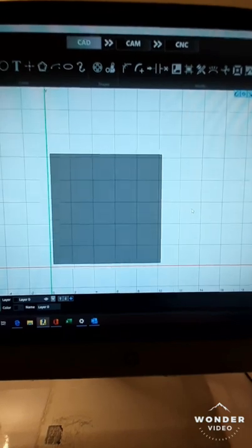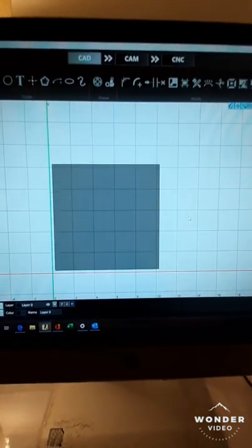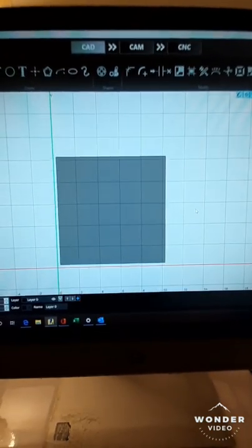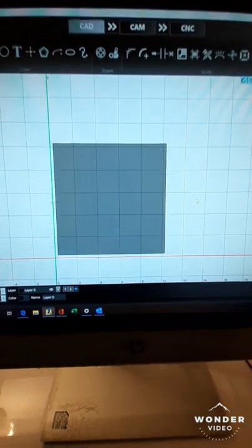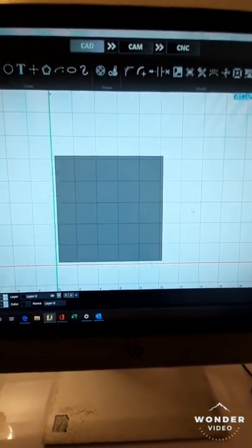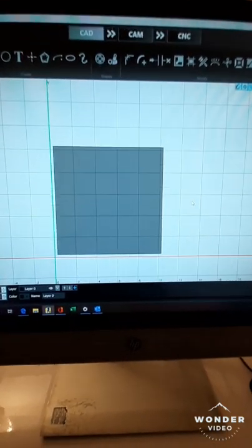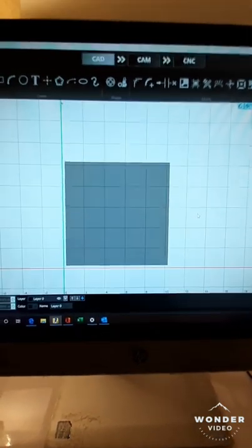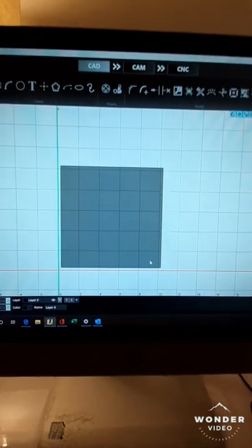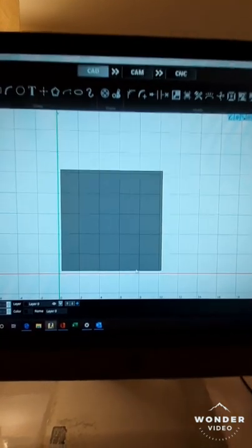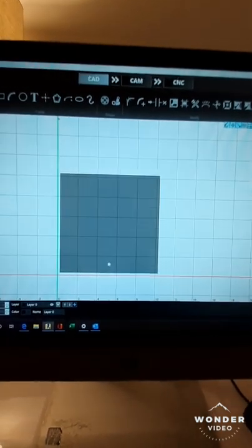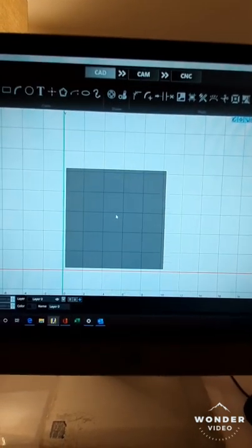And as you can see, we have accomplished a great deal. We took 4 random lines, and once again, through parameters manipulation, through the extension feature, through the trim feature, and also through the move feature, we turned those 4 random lines into a perfect 10 by 10 box. I'm going to leave the lesson here today, and I believe tomorrow we will get into squares, rectangles, and manipulation of both.